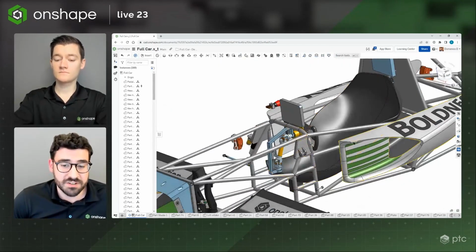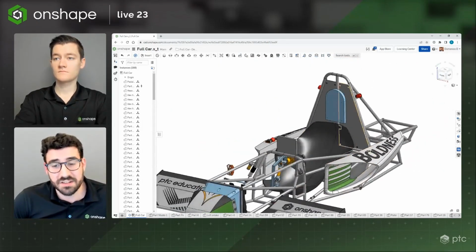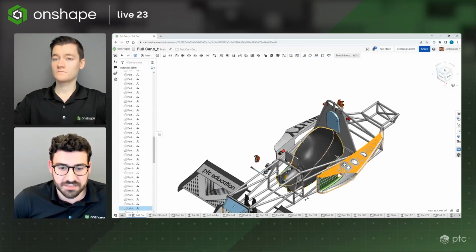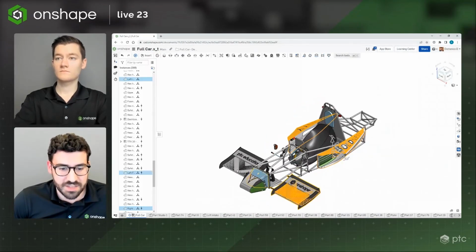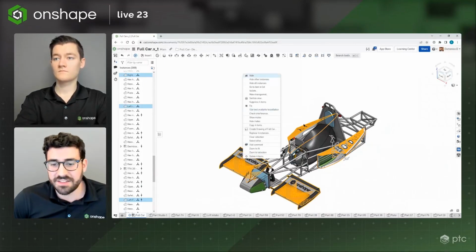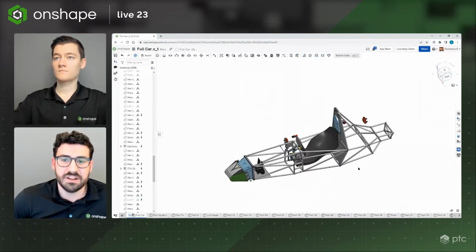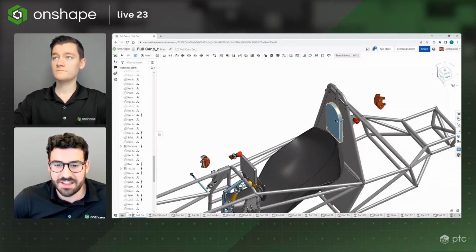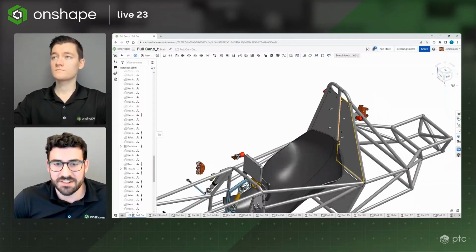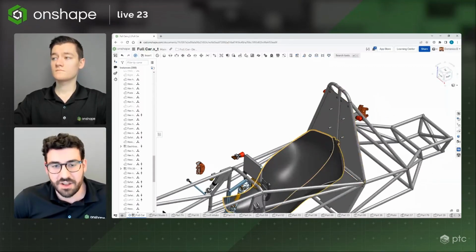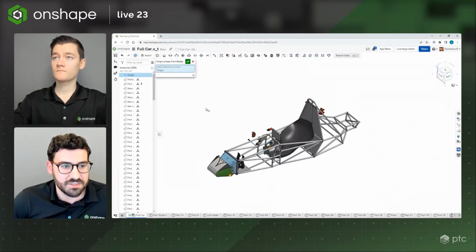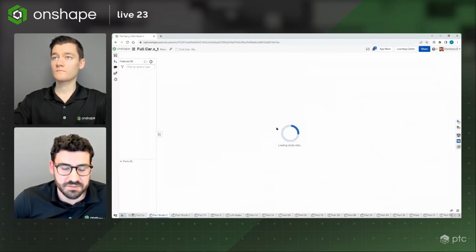You can also create new parts using the assembly with in-context modeling. So say we wanted to create a new headrest back here. You can set up this model for in-context modeling. And the way to generally do that is to go ahead and click on the things that you don't need to see in your in-context modeling. So if I'm just concerned about this, I don't really need to see the rest of it. And I actually don't need that anymore. And so you can see there are these posts here that I might be designing around along with the seat. So I'll go ahead and create a new part studio in context. I'll click the origin and we'll hop into this new part studio.